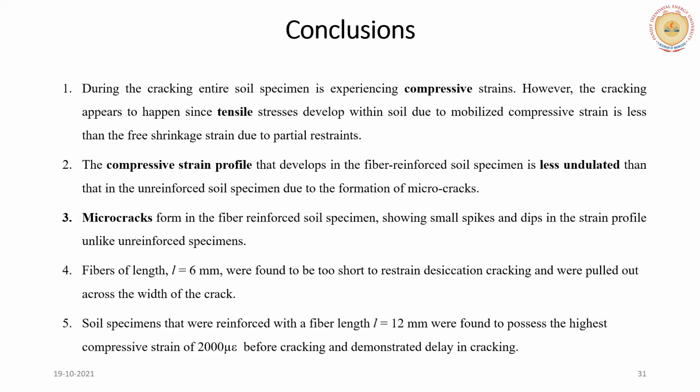And the compressive strain profile that is developed in a fiber reinforced soil is less undulated. As I showed you in the previous photographs, there is less abrupt cracking because of that, right? When it is compared with the unreinforced soil specimen.